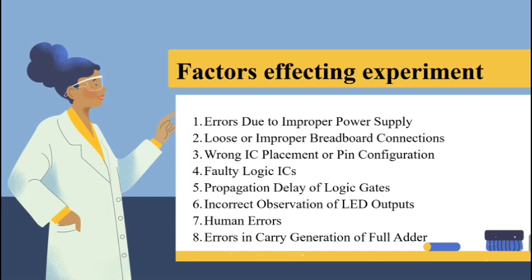Carry out depends on several intermediate signals. The total delay may cause a temporary glitch in the sum and or carry output. To prevent that, allow enough time before observing outputs. Use an oscilloscope for detailed time analysis.